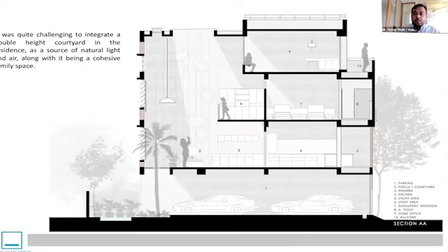The section from the courtyard, but like we wanted to have a triple heighted courtyard which allowed light, but at the same time were also kind of transferring the hot air at the upper level. So turbo ventilators were introduced, and louvers which were hand operated even at the higher level were introduced into this, which allowed enough of cross ventilation. As I already mentioned, it's very important in case of Surat to have cross ventilation because of the humid nature